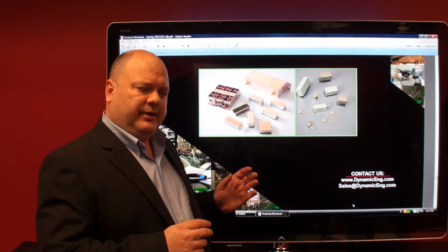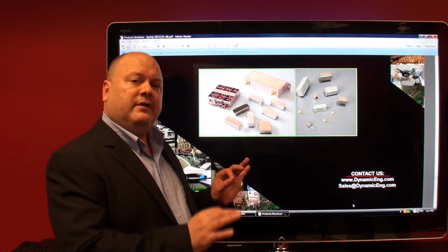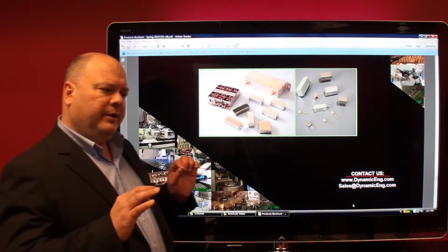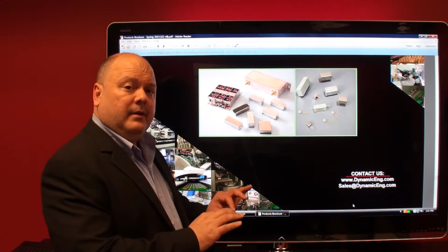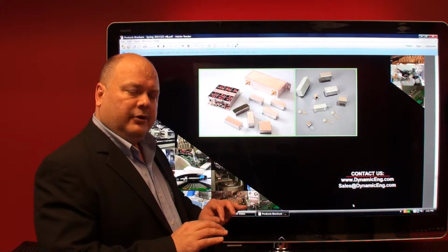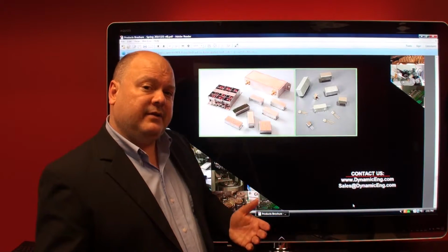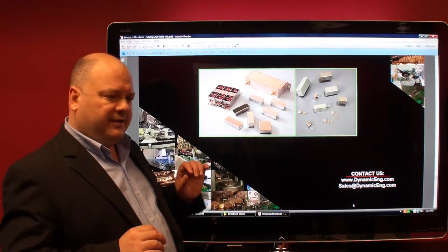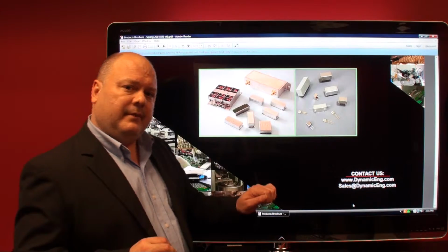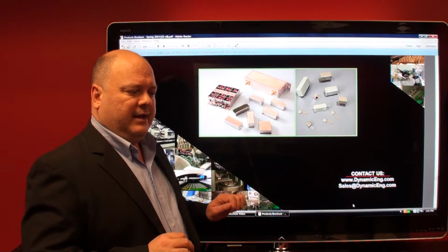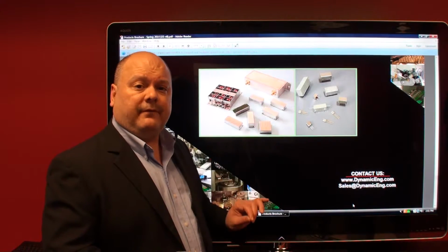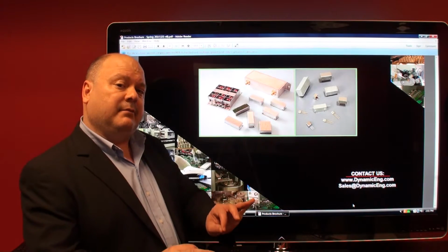All the crystals that are finished, the relationship between the 4 crystals, let's say if 4 crystals are used, they go into test fixtures to match up the crystals with each other. So if you've got an order for 100 pieces, each filter uses 4 crystals. Part of the process is matching the 4 crystals ahead of time with each other, so that each production unit in that 100-piece order has matched crystals up front before putting it in the assembly.